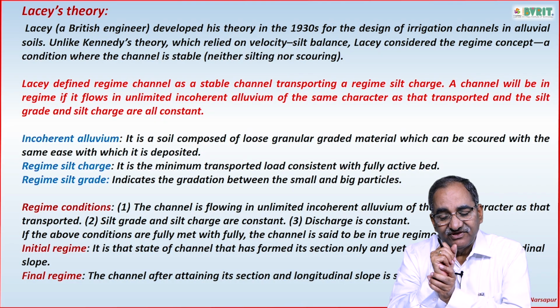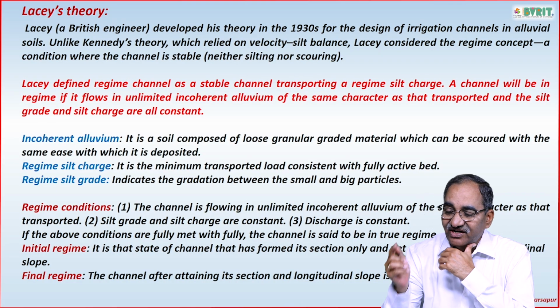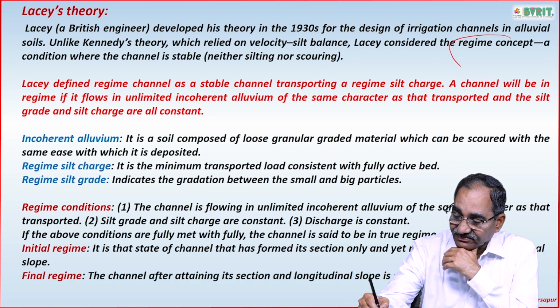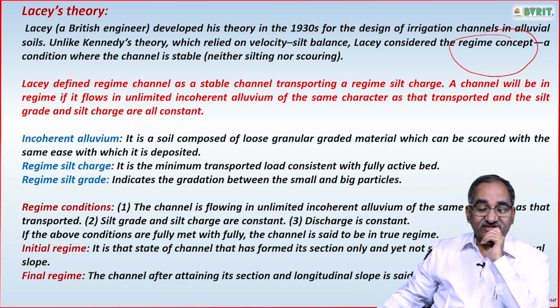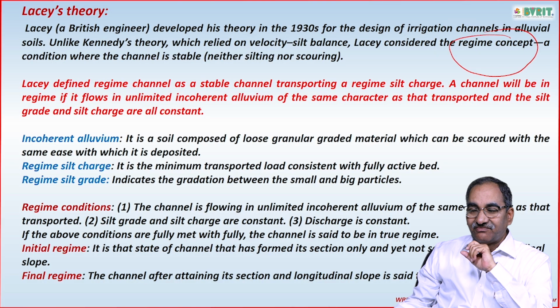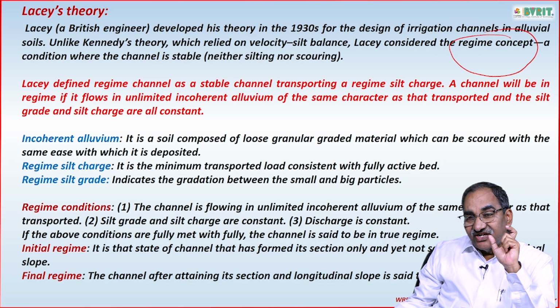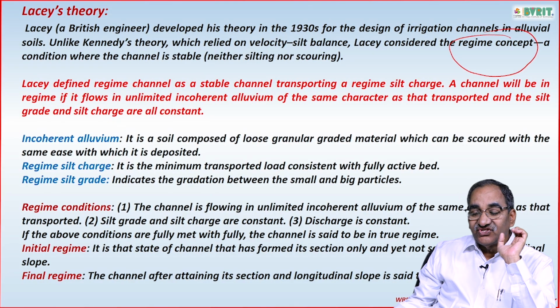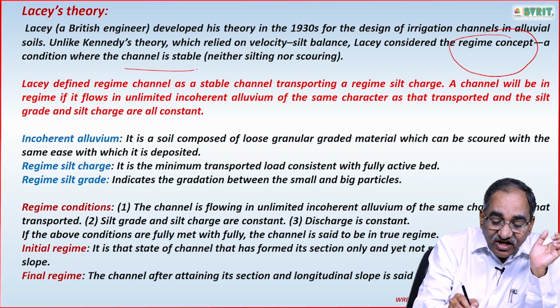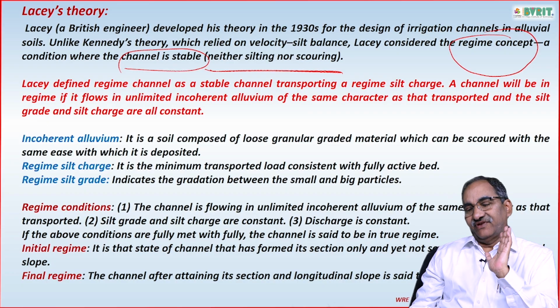Unlike Kennedy's theory, which relied on velocity-silt balance, Lacey considered the regime concept. That is the first difference. Regime condition means the condition is such that the channel is stable, in the sense that it is neither silting nor scouring.